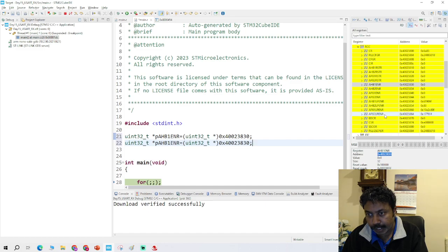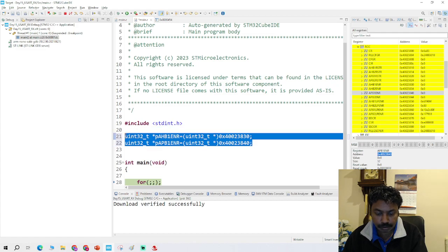Okay, so now you need to set the USART to enable, so I'm just copying that. For the USART enable, you already learned that it's connected to the peripheral bus 1, so you need this enable to clock for the peripheral bus. So copy this, APB1ENR as a pointer, and you have to copy this address as well. So copy that and paste it here. That's good.